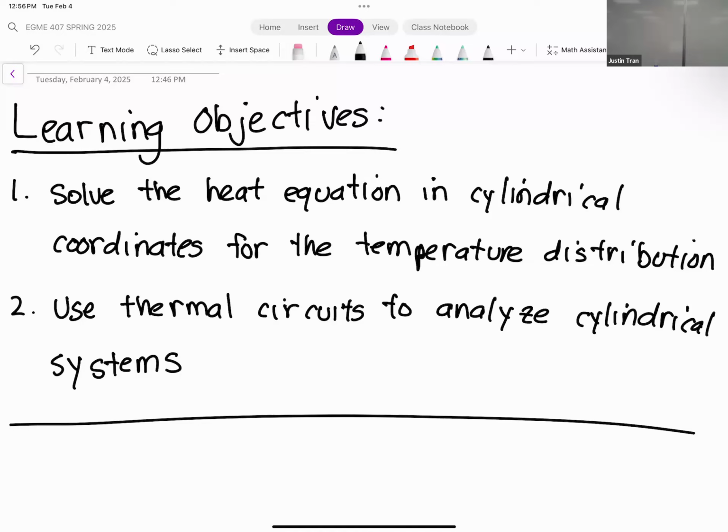On my assumptions here, I put that x equals 0 is specified heat transfer, x equals L is the convection boundary condition, and then specified temperature because that's going to be happening throughout it, or am I being redundant? You're being a little bit. There's only two boundary conditions. There's one on the left side, which is what you have here, so perfect. And then at x equal to L you have convection, so that's your other boundary condition. A specified temperature is only used when we know for sure what the temperature of the particular surface is, which in this case we don't. We know the heat transfer on one side and convection on the other side.